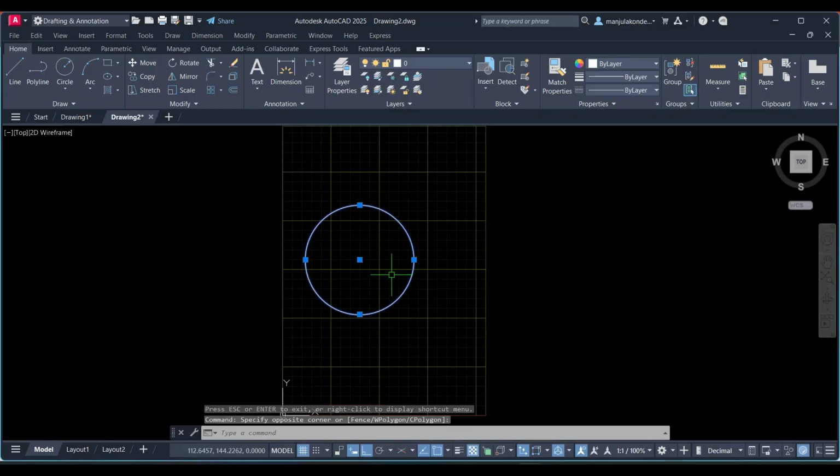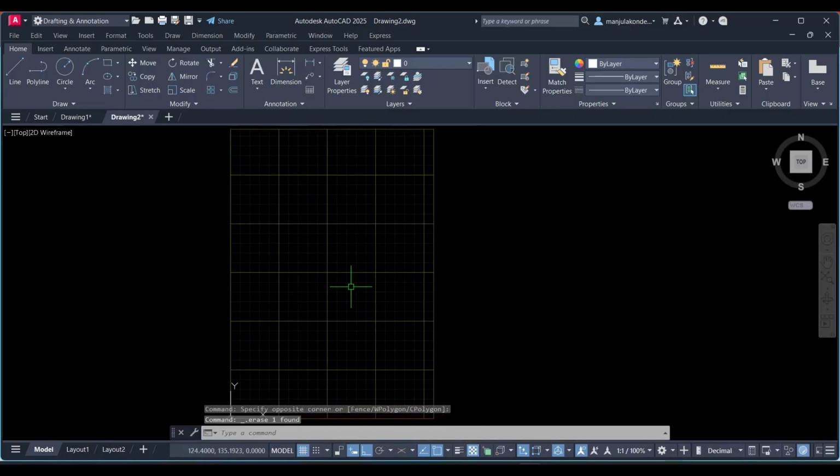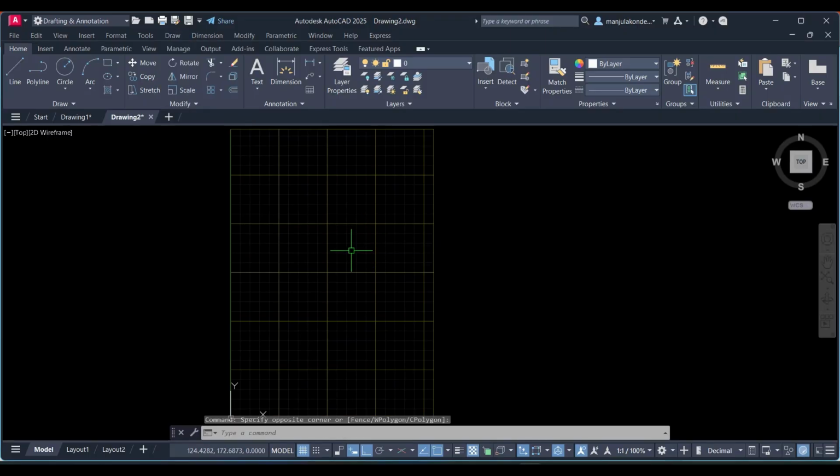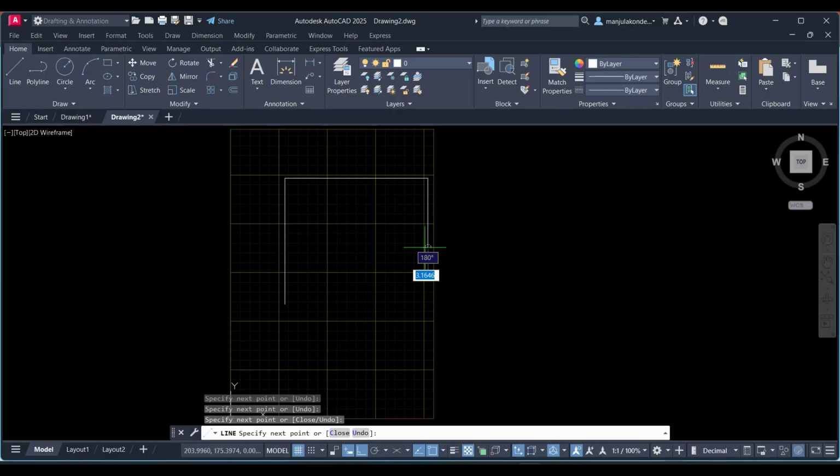Yes. So we are done with the unit, limit and zoom and its types. The first tool is line. You can access the line command from this, or you can access the same thing from the draw menu bar, and the shortcut to increase the work speed is L enter, and you can work with the line command.